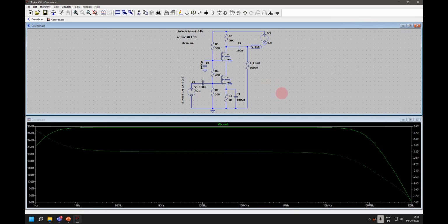Most of the circuits we are going to use will have capacitive load or resistive load? It depends on the application. When I speak about digital design, most of the circuits will be driving the gate of another transistor, which will definitely be a capacitive load. For analog circuits, in real-time applications we might be driving a sensor or anything else, so you can't really specify the load.